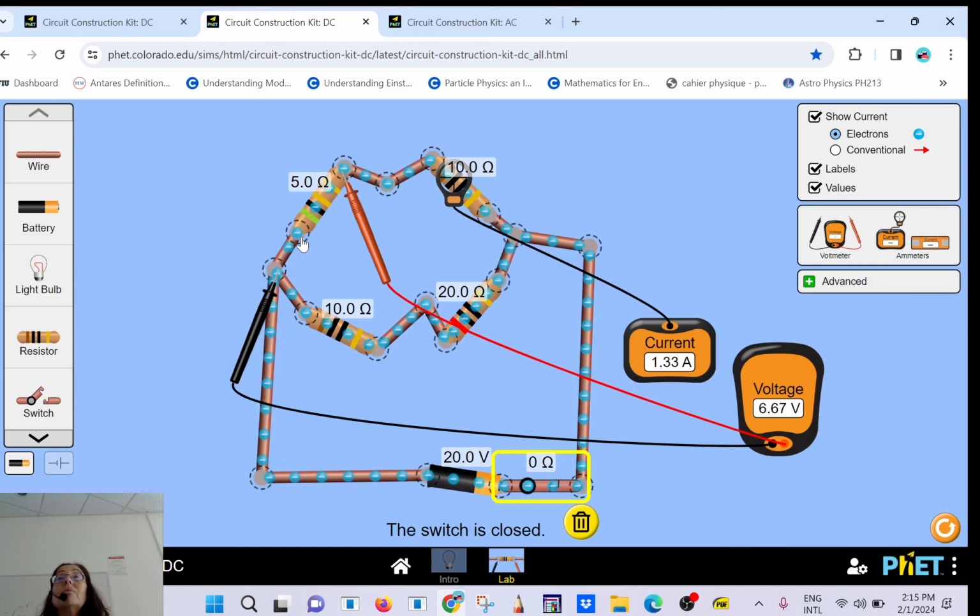Because it's connected to your outlet, the frequency here is the same, so the period is about 0.02 second. If you do the current as a function of time, what's going to be the peak value? 4.3, and it's going to go up and down and up and down, right? And the cycle is still 0.02 seconds.